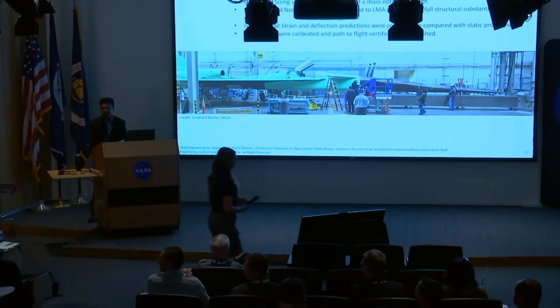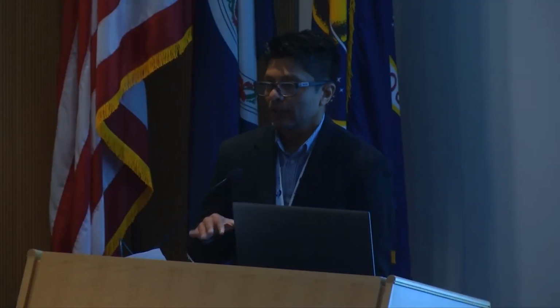For the testing, were you given any test cases to do analysis for, or was all the testing handled by Lockheed? Yeah, for the nose cone, it's all Lockheed. They didn't specify anything even for us to go and test. But for the inlet duct, we had to build small test pieces. There was a T-flange that was bonded onto the duct. So we did some of our own testing that was not required by Lockheed, but we just wanted to make sure our model and modeling methods were correct. So we did some testing for the duct, but not for the nose cone.